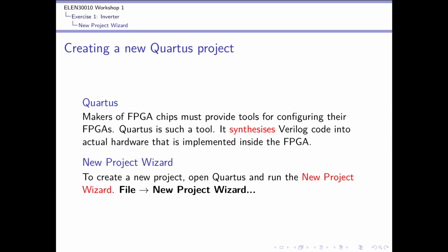That's quite hard to do. It takes Quartus a long time to do it. The compile times are quite long, and it can lead to much confusion and problems unless you get experienced with it through practice. When we use Verilog code to create hardware, it's called synthesis.